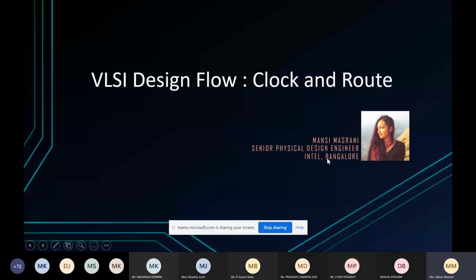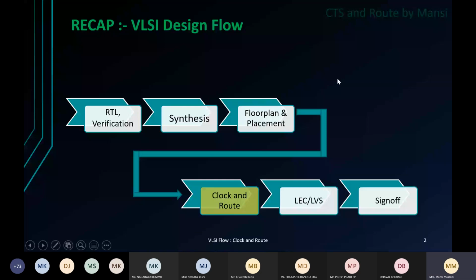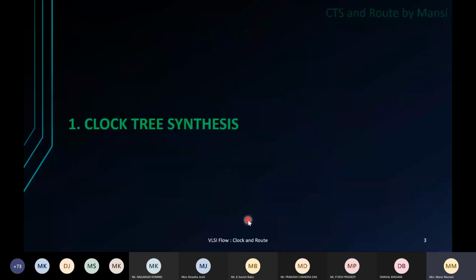So I believe we have gone through synthesis one day before, and today there was a second session where we studied floor plan and placement. That's what the VLSI flow consists of, which starts with RTL verification, synthesis, floor plan and placement, and today is where we will talk about clock and route.